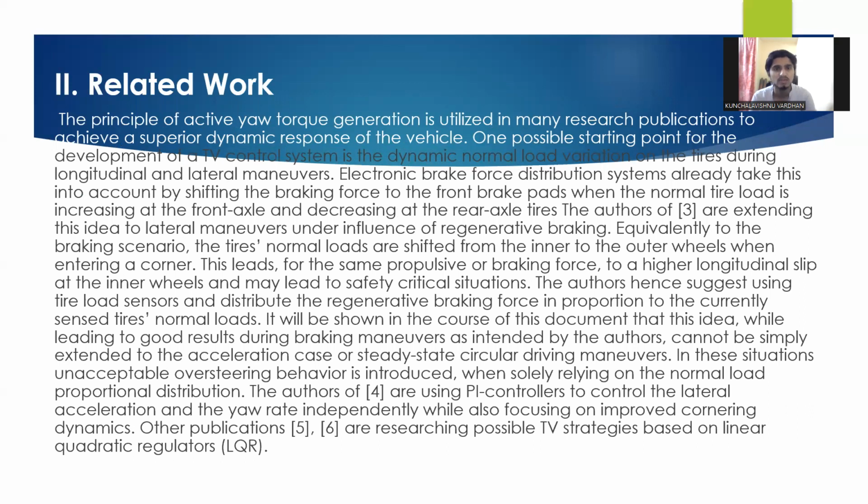The principle of active torque generation is utilized in many research publications to achieve a superior dynamic response of the vehicle. One possible starting point for the development of a TV control system is the dynamic normal load variations on the tires during longitudinal and lateral maneuvers. Electronic brake force distribution systems already take this into account by shifting the braking force to the front brake pads when the normal tire load is increasing at the front axle and decreasing at the rear axle.